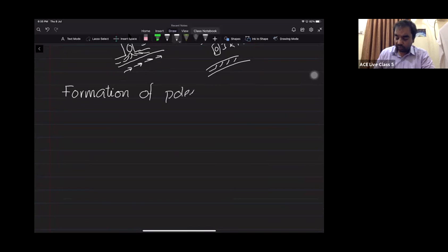See, yesterday, when I was explaining the concept of electrical angle and mechanical angle, the angle which we see with naked eyes we call mechanical, and the one we cannot see with the naked eyes, in short, we call electrical. But we can imagine if it is a 4-pole machine, the electrical angle will be 720. If it is a 2-pole machine, the electrical angle will be 360. Why? Because north to south is 180, south to north is 180. Like that, you can decide, right?